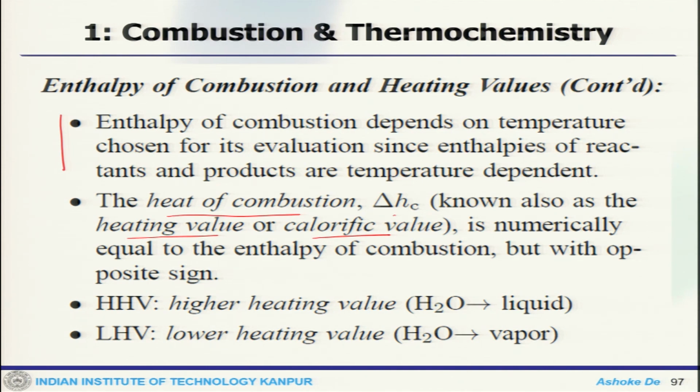And there are two different types of heating values. One is the higher heating value, and another is the lower heating value, and that depends on what you get as product H2O. If the H2O in the product is in liquid form, then you get the higher heating value, and when the H2O in the product is in vapor state, it is the lower heating value.